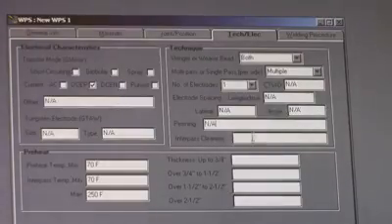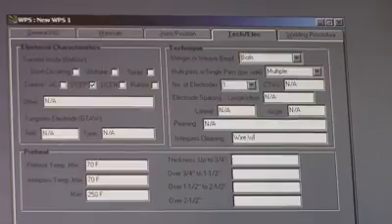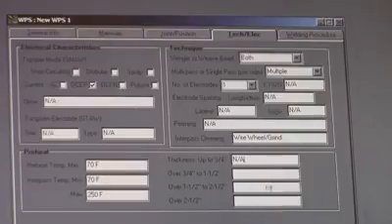Interpass cleaning: wire wheel slash grind. And this is more preheat stuff. It's over our thickness, so we don't care. We're just going to NA out of there.